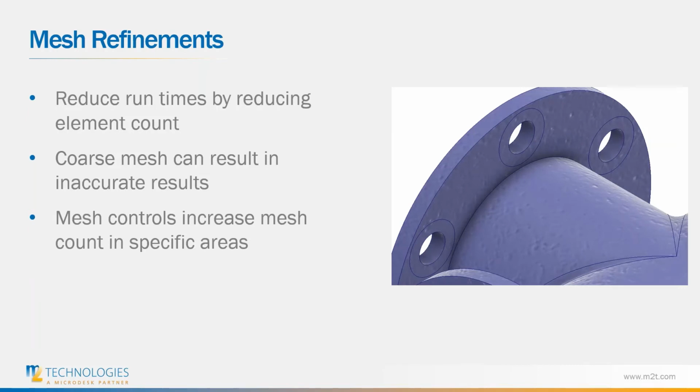Lastly, before we run, we need to define the mesh. This is where the refinement for how long a study is going to take really comes into play. The mesh is going to define where the calculations and the interactions between mesh points is taking place. You can see in this picture we already have 3 rings split around our bolt holes. This is to model where the washer will be interacting with the flange.